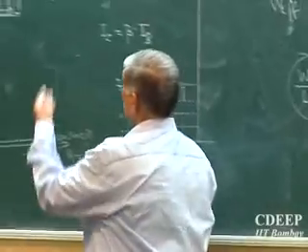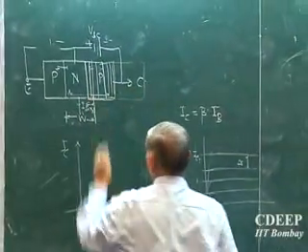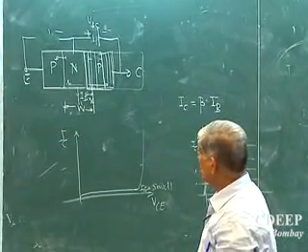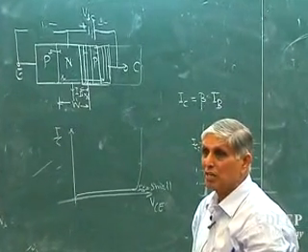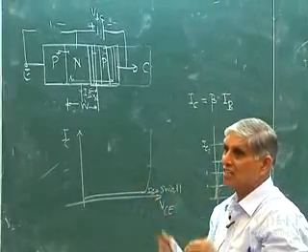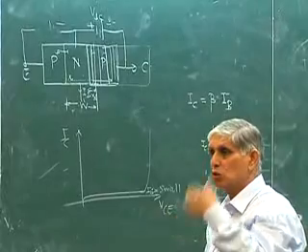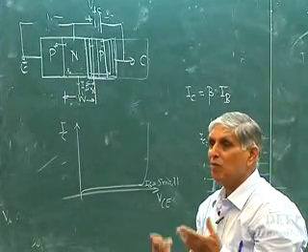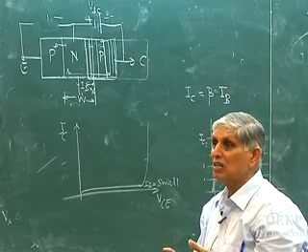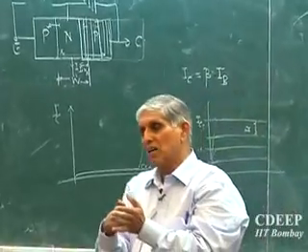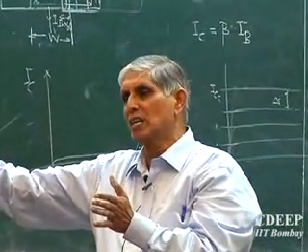Alternatively, even if this is wider and it's not punching through, at this base collector junction, because you are increasing VBC, the depletion width is enhancing, so your electric field is also enhancing. Which effect can then come? Avalanche. Avalanche breakdown can also occur if, let's say, your collector length is too long and it never gets punched.